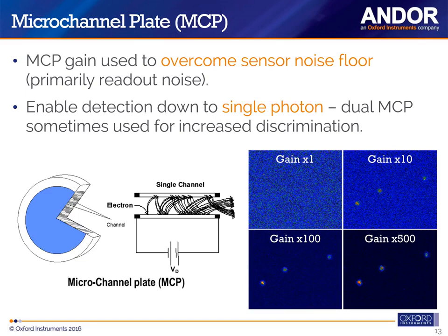Microchannel plates are made of all of these little different channels here, and incoming photoelectrons to the MCP hit the wall of the channels and can create a secondary photoelectron. There is a voltage difference between the input of the MCP and the output of the MCP, creating an electric field, and the photoelectrons are accelerated and by impact ionization multiply and create a cloud of photoelectrons. That's the principle of the amplification.